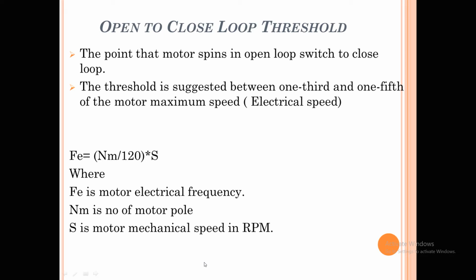To get sufficient back EMF sensing, we need to get the motor RPM to a certain extent. Once it reaches that particular RPM, you are sensing your back EMF value in a proper way, so now you are capable of switching your motor operation to closed loop.